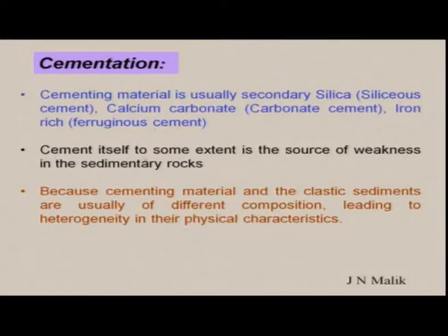Okay, so cement itself to some extent is a source of weakness to sedimentary rocks, as we discussed in the previous slide, because the cementing material and the clastic sediments are usually of different composition. So you will have the clasts of one composition, and the cement of a different composition. So that is a heterogeneity which we will have, leading to heterogeneity of their physical characteristics. So this is one important part of the cement which you can remember: either it is siliceous, carbonate rich, or iron rich cement.